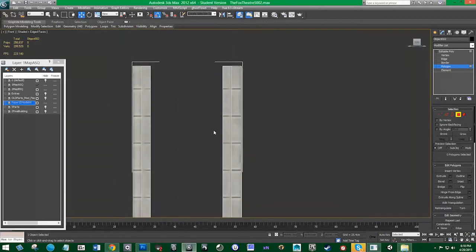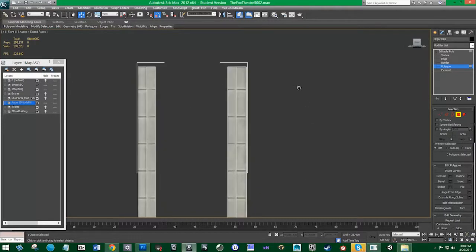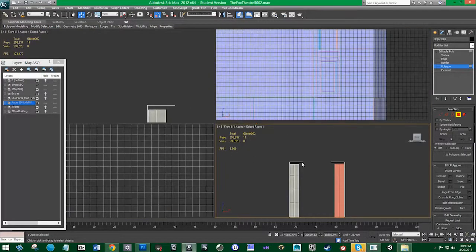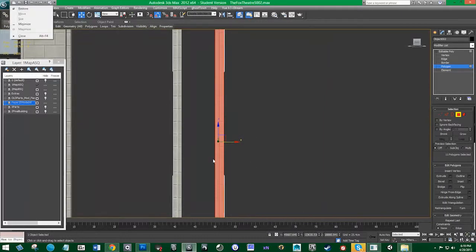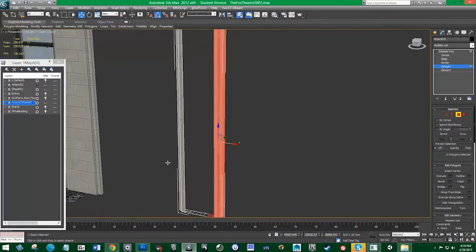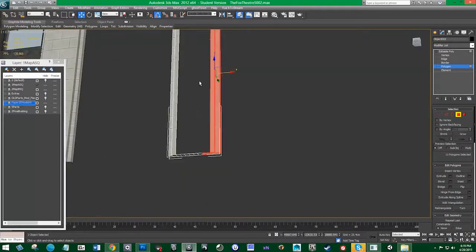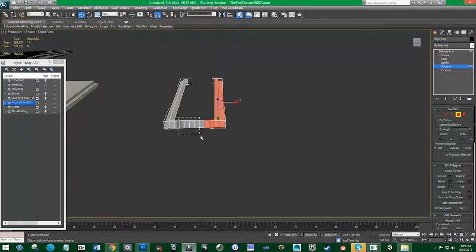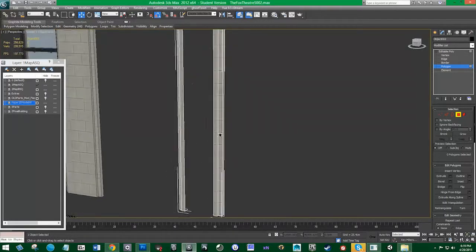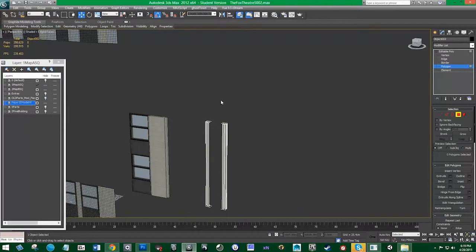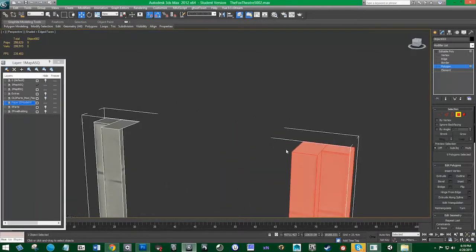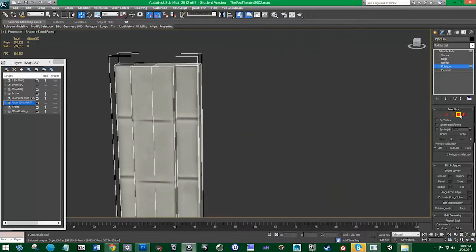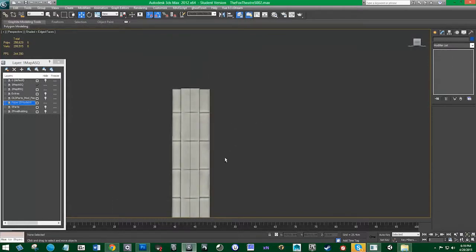Okay, so I'm also going to select these and go back to our perspective view, and I'm going to snap them together. But first let's delete these bottom faces here, and then I'm just going to go and grab these faces, hit S for snap, and then I'm going to snap these to these other ones here. Okay, so now I think that'll be our piece there.